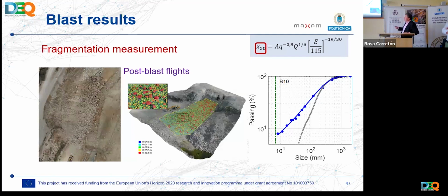Because there are a number of errors waiting for you when you do the size distribution analysis. Many errors, and you will run into them. You can't avoid them. Some of them are physical. It's impossible to get a good and exact fragment size distribution similar to the one you get by sieving. Impossible. But you can go around some of the errors, and if you can get some fragmentation data elsewhere, for instance in the plant, then you can come to a reasonably good fragment size distribution curve